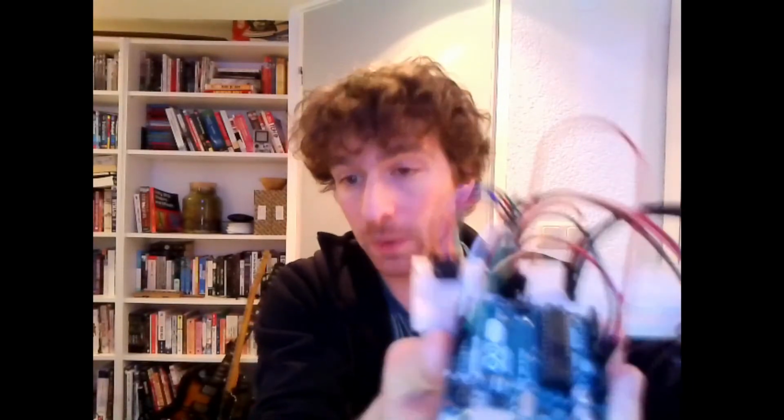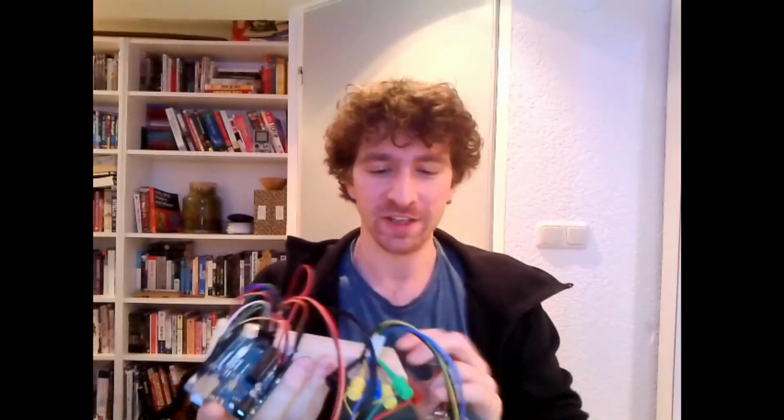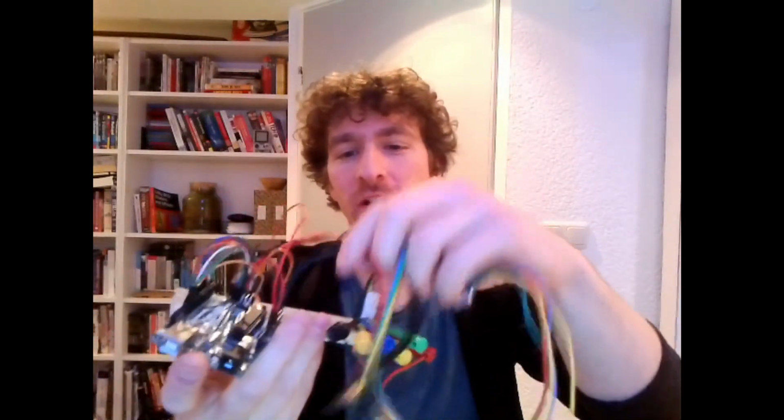So I've got a level shifter there, and I've got basically the same kind of setup where I can plug in the module and the logic analyzer. I've got a bunch of wire harnesses ready so I can plug the logic analyzer in. That is because I needed a sane place to see how you properly talk to this card. I've been reading a lot of theory, but I wanted to see how the signals were looking. So I've been observing the signals on the Arduino and also then applying them to the Bus Pirate.